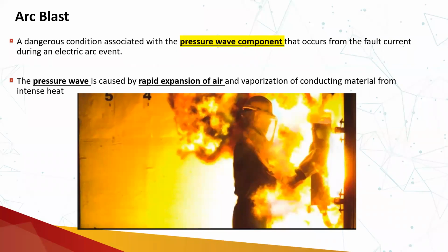An electric arc can occur due to failure of insulation, a narrow gap between the bus bars, a dropped tool, or any other reason. Maybe there is moisture and the air is contaminated, so the gap between the conductors has narrowed. This might result in an electric arc.